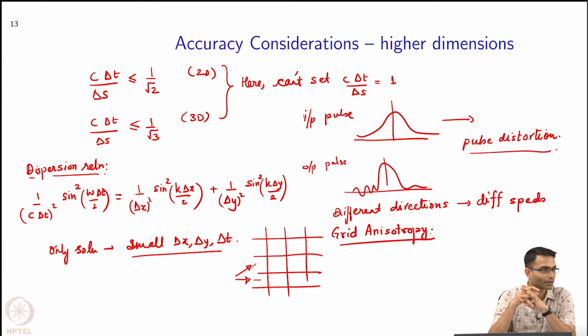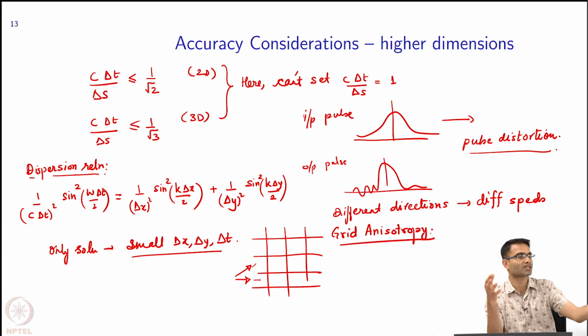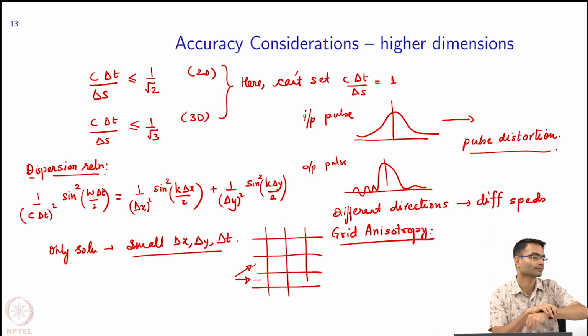So if you take a Gaussian pulse in time, it's Gaussian in frequency. Well, in FDTD I don't have to worry about that. I've discretized delta x, delta t. Once I set my source, the wave travels. That the update equations take care of.